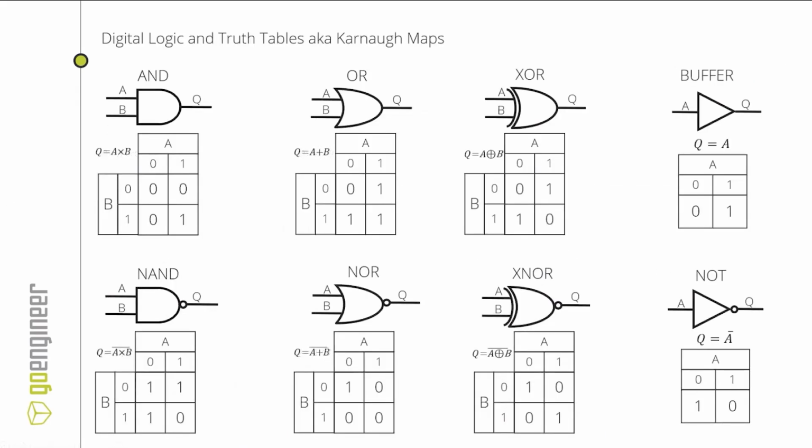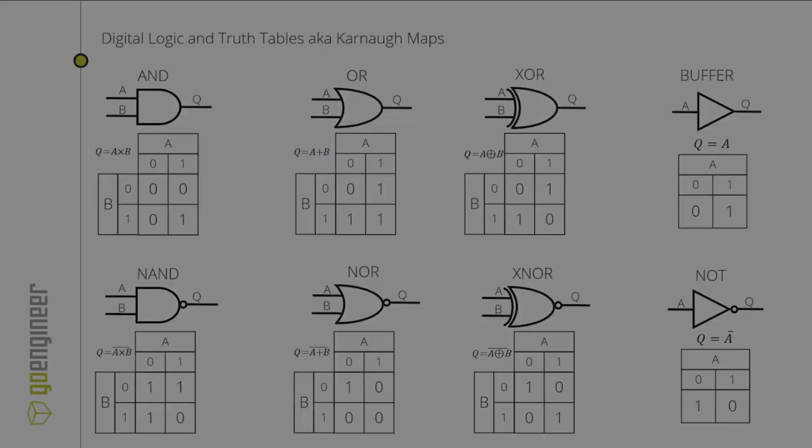And so depending on what my pulse is and what moment of time I'm in, all of these gates are outputting a specific value. For my minute circuit and for my second circuit, I used a couple of AND gates that were connected to my CD4510. I'll show you that in a little bit. But what I wanted to do was reset some of the CD4510s back to 0 once the value hits 6 for 60 seconds and 60 minutes.